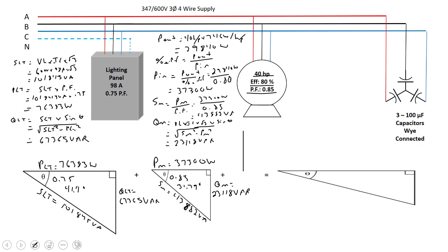Let's go ahead and work on our capacitor here. I'm going to take a little bit of a longer process on this one, right from the beginning. There are shortcuts you can take, and when we get to power factor correction, we'll explore those shortcuts a little bit more. In this case, we've got three 100 microfarad capacitors connected in Y. This is a 60 hertz circuit, so we are going to convert that over to its reactance at 60 hertz for each one of them. So XC is 1 over 2 pi f C, and if we sub that in, we should get around 26.53 ohms.